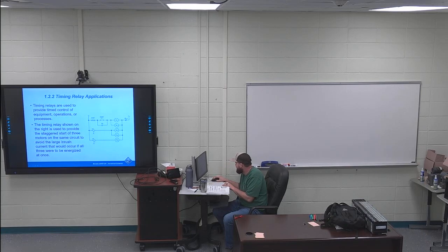So motor 2 and TR2 after a time delay are started up. While TR2 is timing, motor M2 is getting up to speed. When TR2 finishes its timing period, the normally open contacts close to energize motor starter M3. So M3 is then energized.